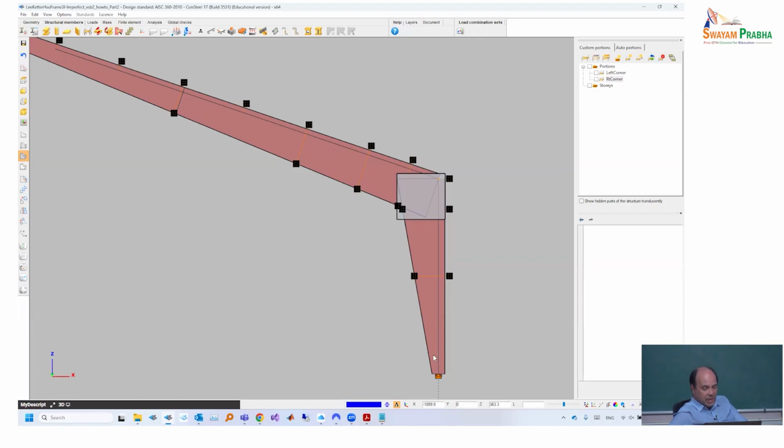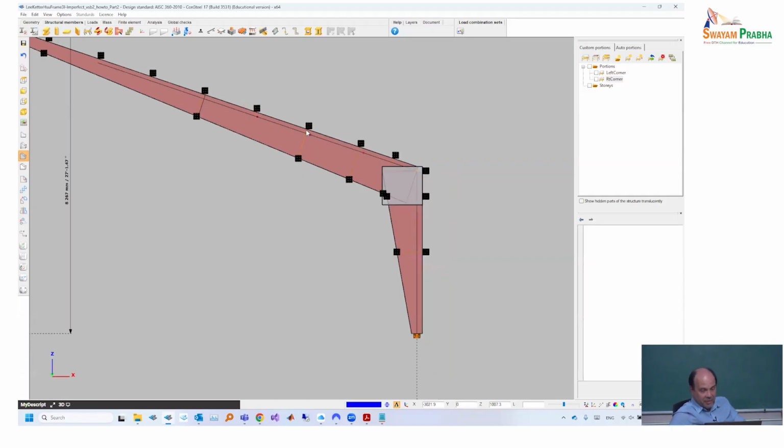So when Consteel would, in that case, start to check the columns from column base up to this point, and then from this point to the top of the rafter, then the design is not complete. So connection design is still missing. That must be performed somehow. And unfortunately here, Consteel cannot help yet. If it was a Eurocode project, then yes. If it's an AISC or Indian standard project, then no. Okay? But now we speak about stability of members.